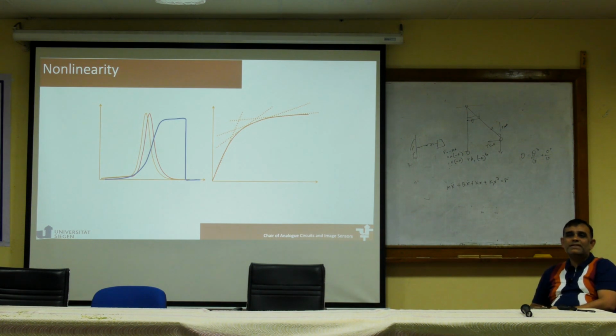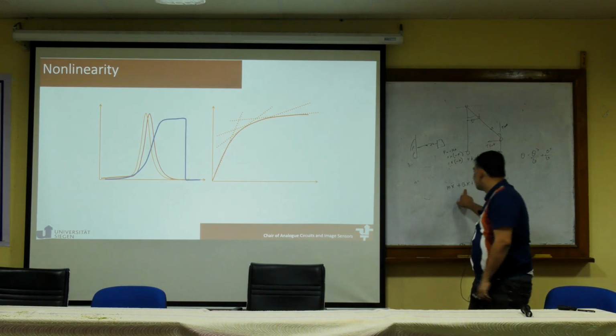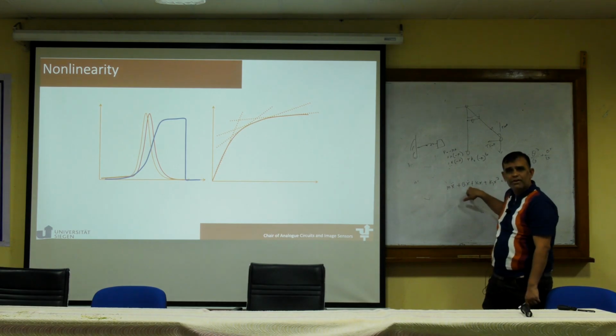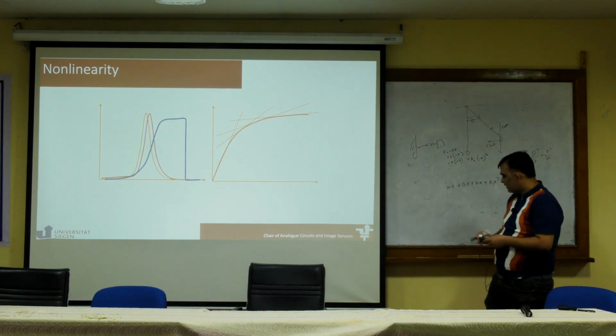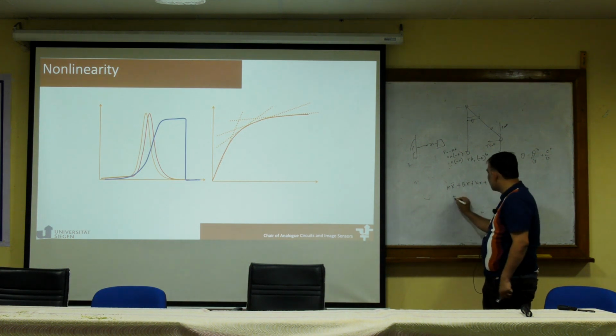So this problem was studied first by Duffing, a German mechanical engineer. And he looked at how mechanical structures move when they have got nonlinearity in their spring constant. There could also be a nonlinearity in this term, the damping. Damping is linear here, it's directly proportional to velocity. Right? We could get a cubic order nonlinearity as well, or we could get more, written as something like this.